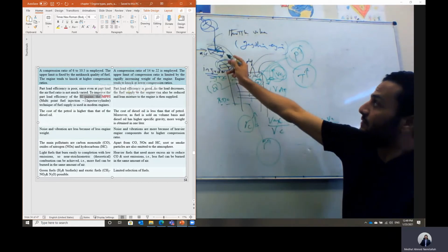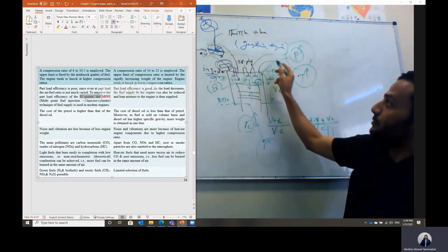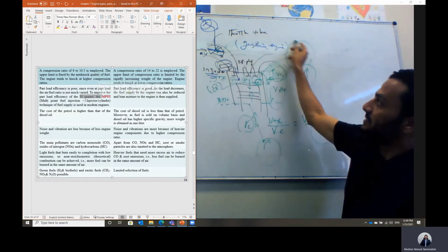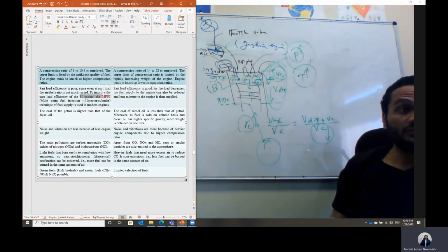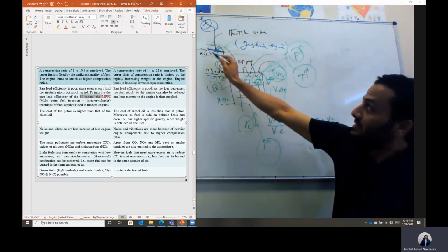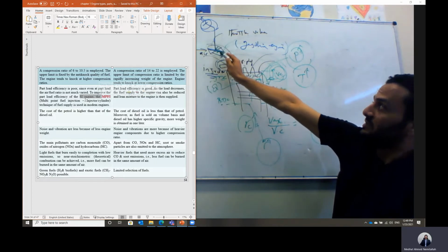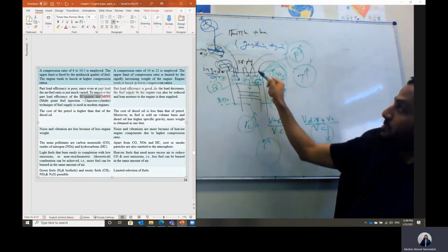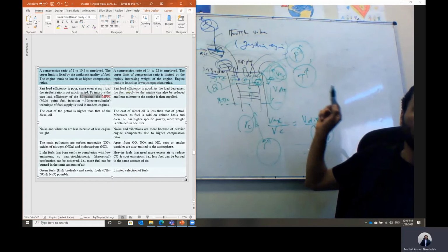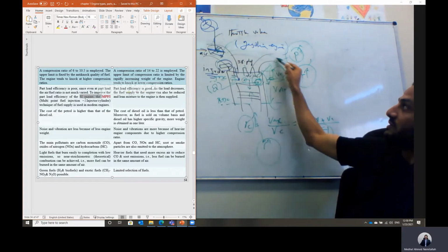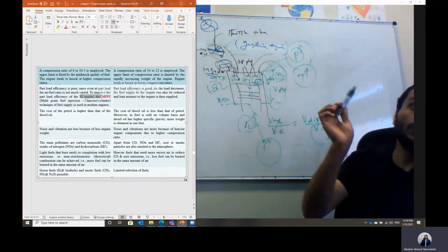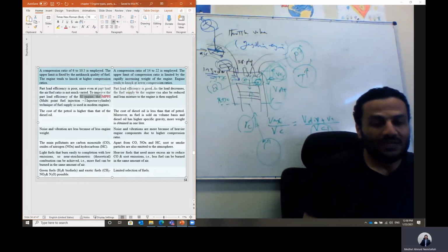And then the flow of air can go directly to this cylinder through the intake manifold, or to the other cylinder, or the third cylinder, or the fourth cylinder, depending on which intake valve is opened and on the firing order. So we have only one throttle valve in the intake manifold with the fuel injector, and this can be distributed to different cylinders depending on which intake valve is open. If this one is open, it will take the charge, and we have only a single fuel injector.